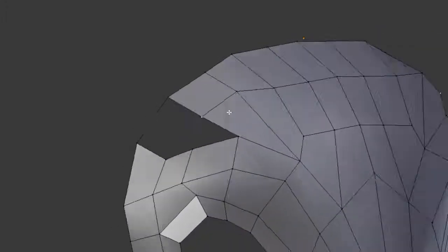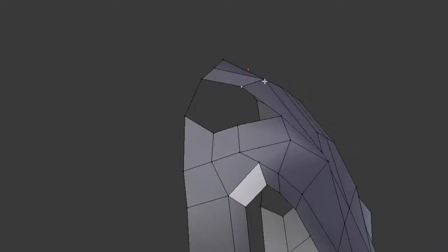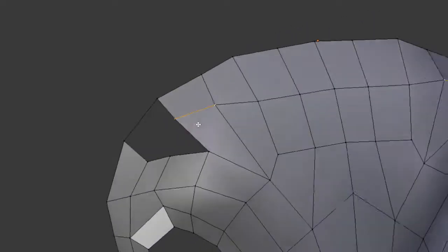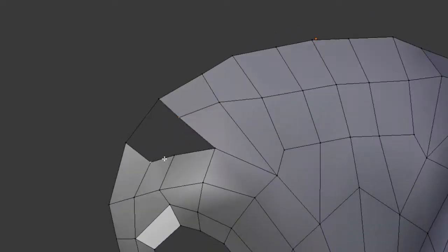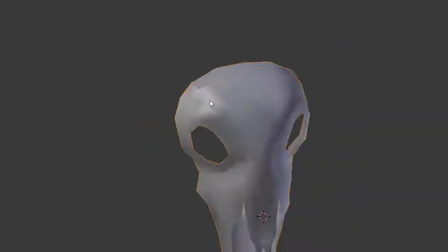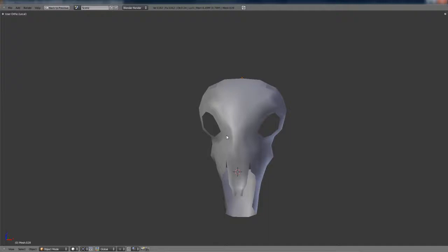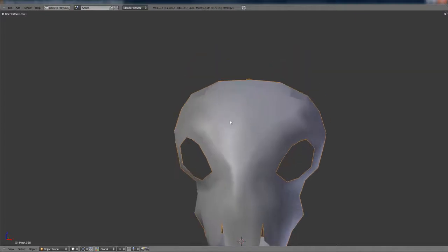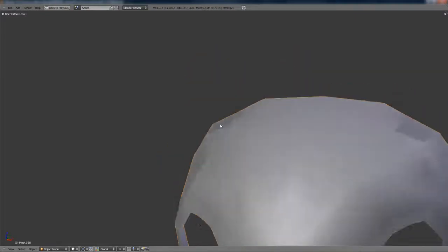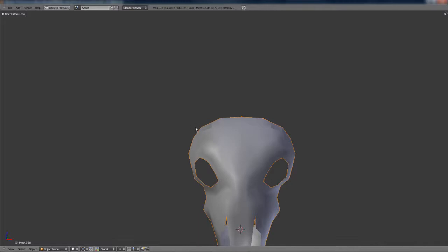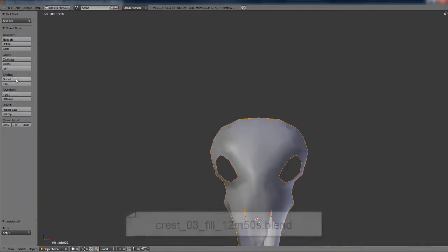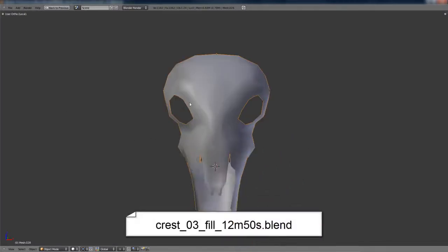Now this area can be quite smooth, so I don't mind adding this large skewed face just above the eyebrow. Really at this point I'm just looking for a way to connect them all together. And that works fairly well. But you can see that there's still just a couple of sharp faces there, so if I just hit T and select smooth again, that should take care of that problem.